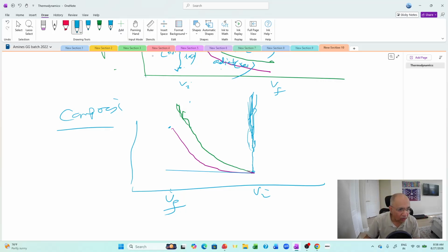So this is undoubtedly same volume, means isochoric process. This same pressure means isobar, and between these two, the adiabat will be above, because in compression there is a temperature increase. I'm so sorry, temperature increase. So temperature will increase, so pressure will be higher, so the adiabat will always be above, and this is isotherm. Accordingly, this is isotherm reversible, adiabat reversible.